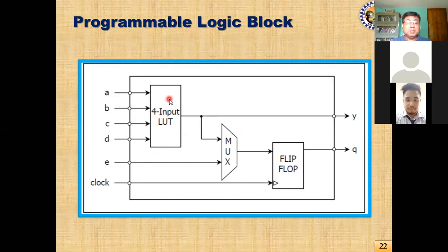We know that multiplexers are referred to as universal logic circuits because multiplexers can implement any type of Boolean function within them. So this is a 16:1 mux. Understand? This is a 16:1 mux where A, B, C, D are the select inputs. So any Boolean function of 4 variables can be implemented inside this LUT, inside this multiplexer.